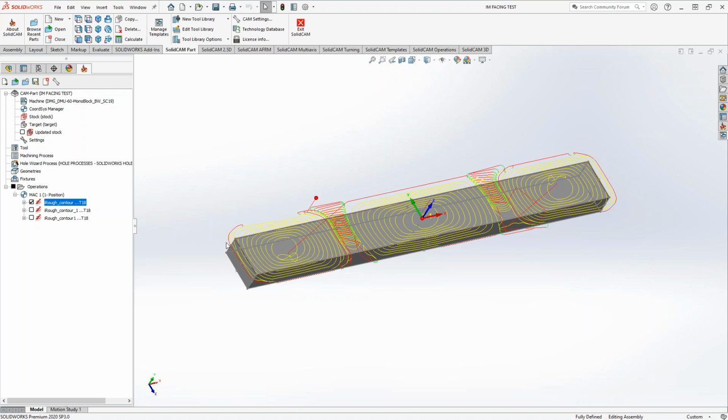You have control. So basically, if we had this path off and we just had a bunch of lines going this way and then a short line and then another long line, what's happening here is we're having one long tool path and then a real short tool path and another long one again. Plus, as we're going along this long path, there's more and more heat that can get built up in that chip and in the part. So by switching it over within the algorithm to breaking it up into basically 3 equal squares, we're keeping in constant contact with that material, and we're not doing the long drawn out steps and then a quick little short step, then a long drawn out again and a short step. Over here, the tool is just staying in constant contact with that material, and you guys should actually see a faster cycle time using this way versus coming over here.